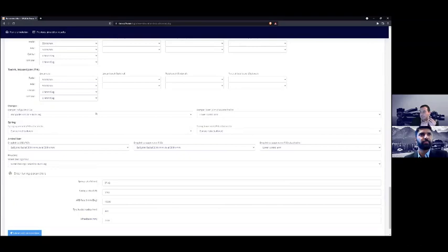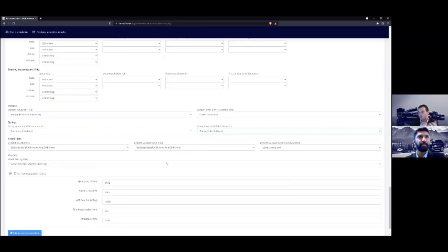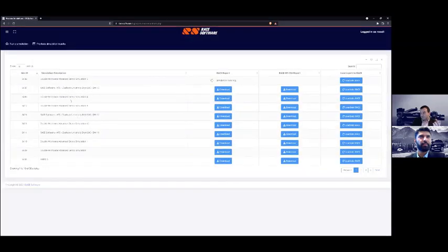After that, the same, you can specify your topology, where the spring is attached to. It's a coilover damper, attached to the chassis. You can specify your wheel bearing stiffness, the spring rate. Again, for the purposes of the demonstration, I'll just use other values. Your anti-roll bar rate, the tire loaded radius, and the wheelbase. We press submit and run simulation, and now again the data is getting packed and it's sent to our servers ready for simulation. As we can see, the previous simulation has already finished, so I'll be presenting you the report.